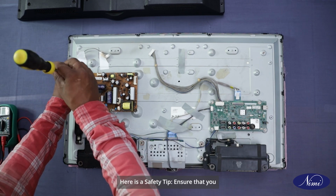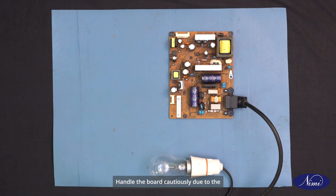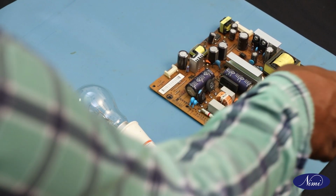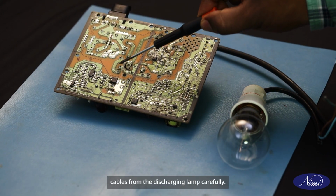Here is a safety tip. Ensure that you gently disconnect these to avoid any damage. Handle the board cautiously due to the fully charged capacitor. Use a discharging tool to safely discharge the capacitor by connecting the cables from the discharging lamp carefully.